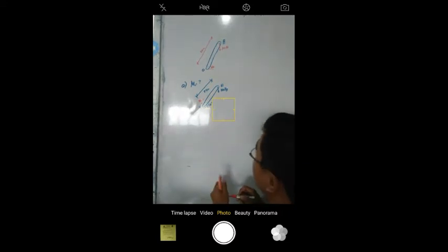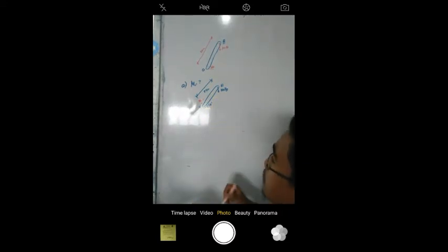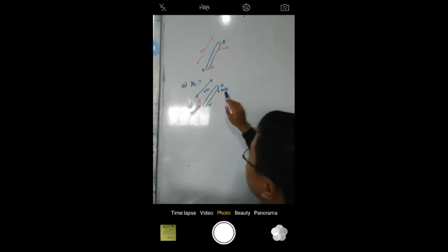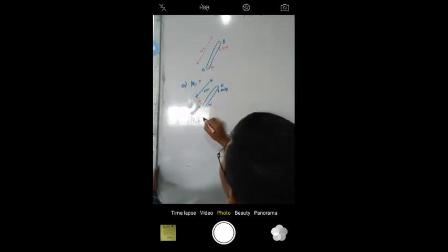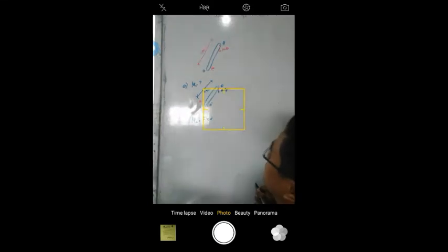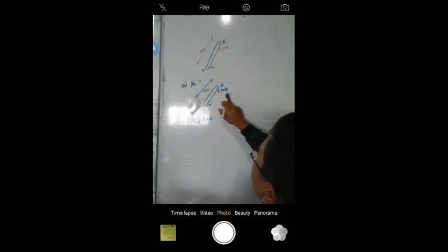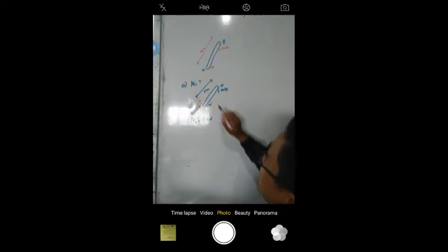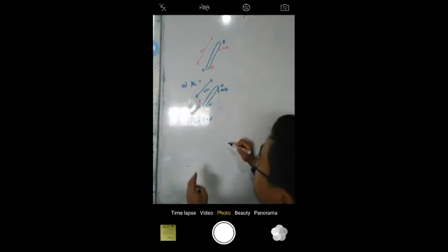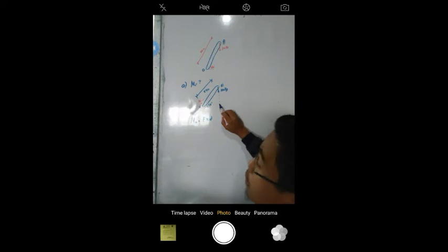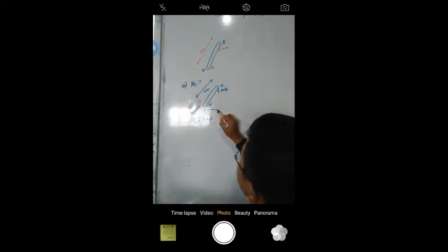So, obviously, whenever we wanted to solve the value of moment, all we need to do is to look for the force. Of course, may force na tayo at saka yung distance. So, again, moment at O is equal to force times the perpendicular distance, right? So, ano yung force natin? Obviously, it's 100 pounds. Pero ano yung distance natin? Is it the 24 inch? Or what? Yung sinasabi natin na distance is the perpendicular distance to the force. So, this is the force. Anong perpendicular distance? Obviously, this is our perpendicular distance, and we denote that as d.